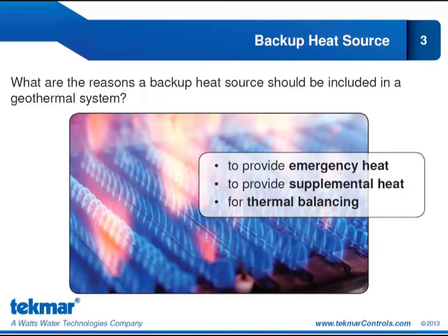So to avoid any scenario like that, we want to make sure that our system is thermally balanced, that we are not extracting more heat than can be recovered. And so we could maybe downsize the amount of heating that our heat pump will provide and make up the rest from a backup heat source. So those are the reasons we'd consider adding a backup heat source.